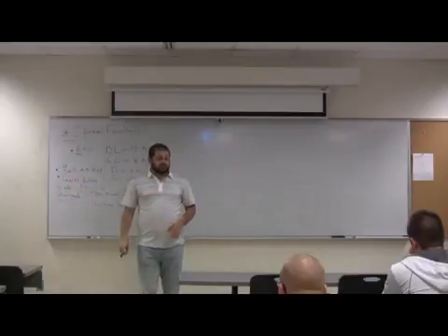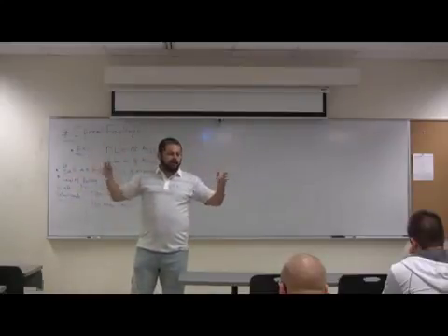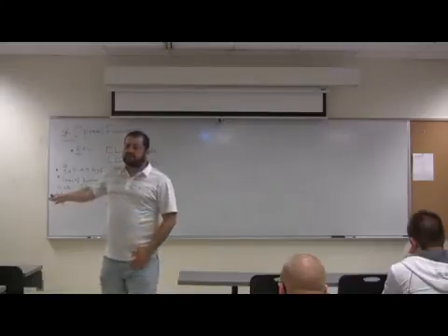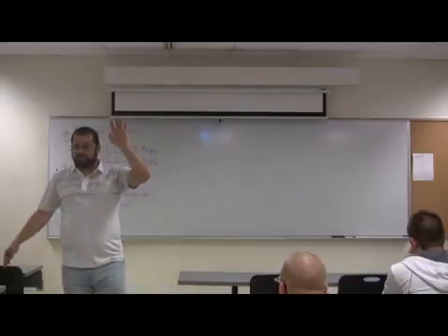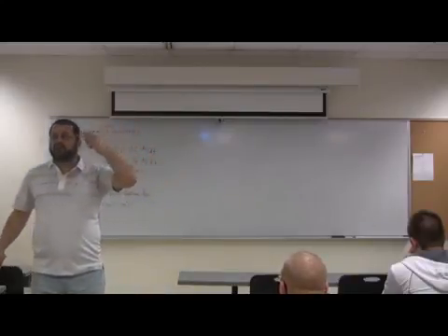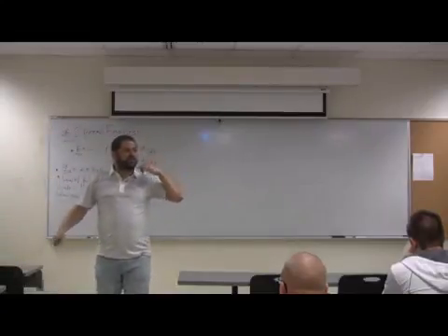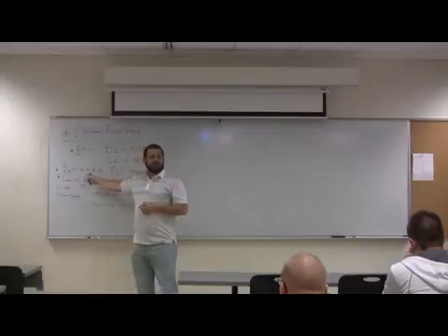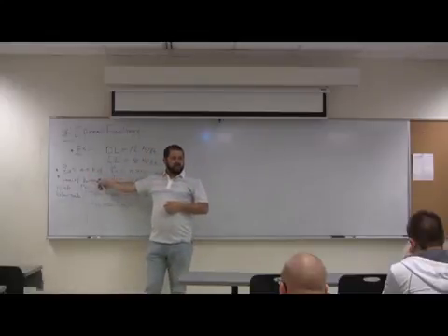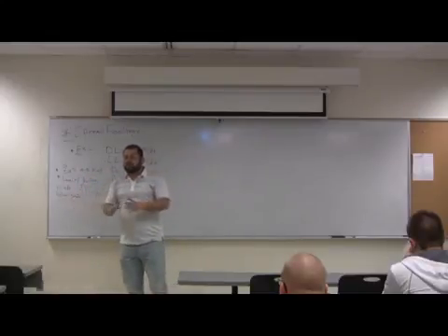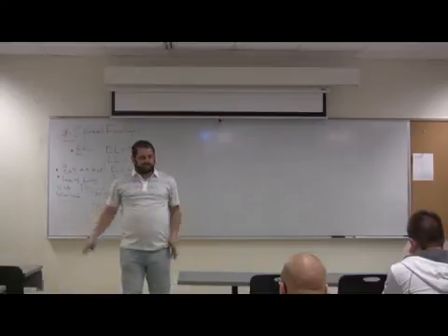From the soil report. You see a lot because the guys here, they use a factor of safety of at least 2.5. The factor of safety there is 2.5 to 3. Okay? Sometimes goes to 5. So there's a huge factor of safety in this value that was given to you. Okay? You use this Q allowable to find the area, just the area of the footing.